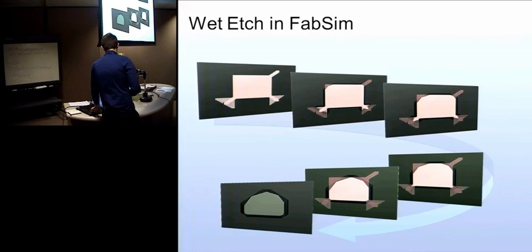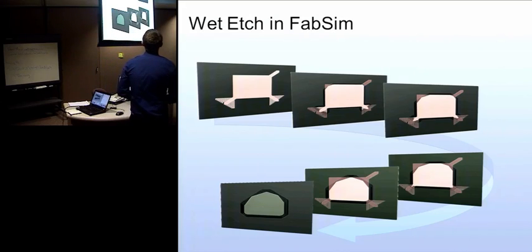Another example would be for wet etch. This is actually one of the hands-on demos. When you do corner compensation analysis, so when you have to modify your layout to get the corners to look the way you want, for this we would recommend using either Intella Etch, our etch tool, or FabSim because it uses a more advanced algorithm where it takes into account these effects.